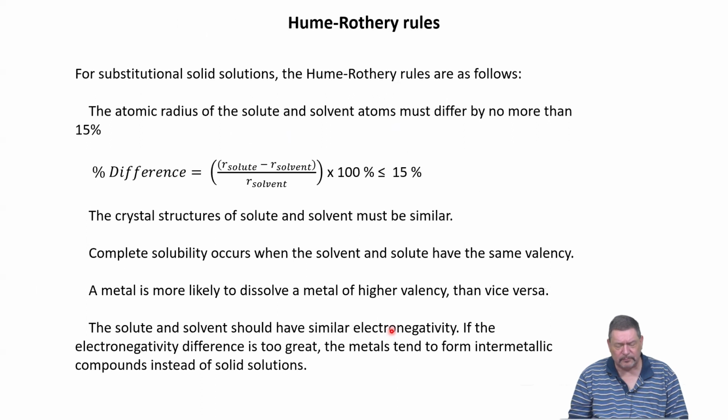Hume-Rothery rules. These are rules for defining ranges where you can find certain intermetallic compounds or phases. Then the electron per atom condition was used. But for this case here, more importantly, is this geometry effect, the atomic radius. So if you want to mix 2 atoms and they should then form a solid solution, mixing on the same crystal lattice, then the atomic radius difference should be less than 15%.